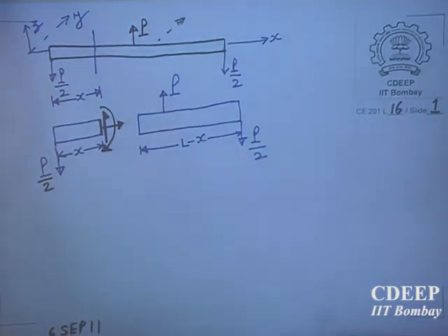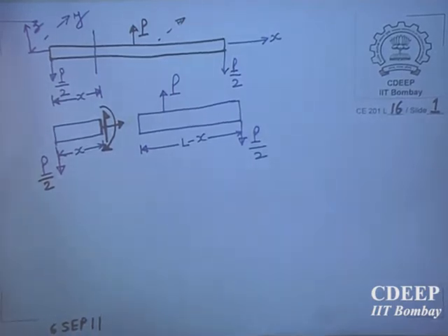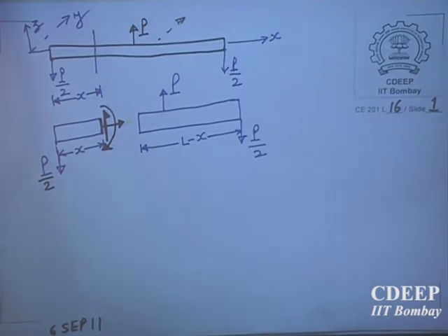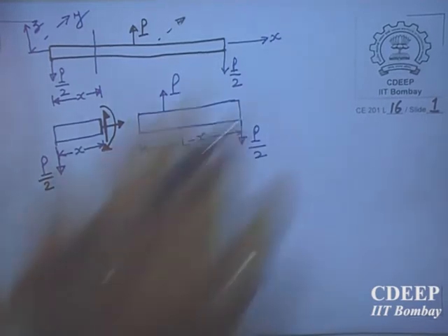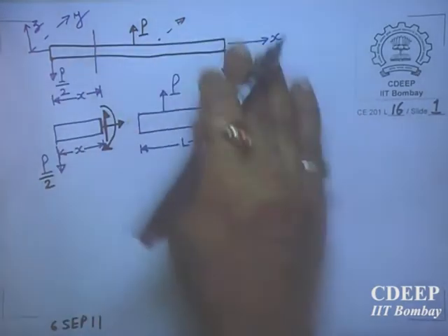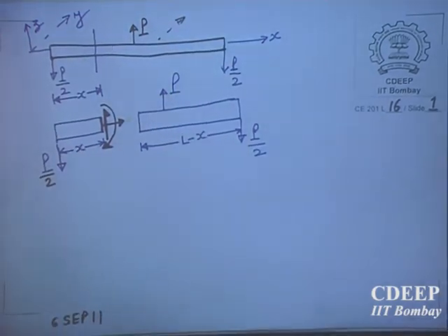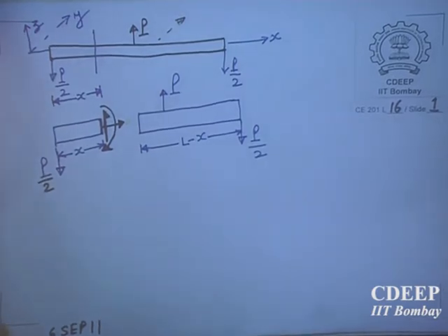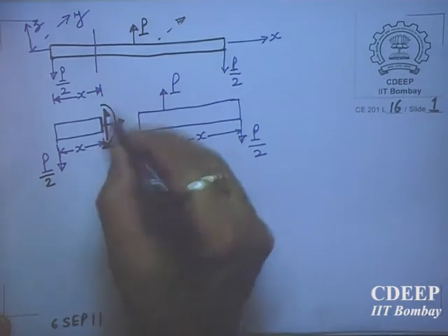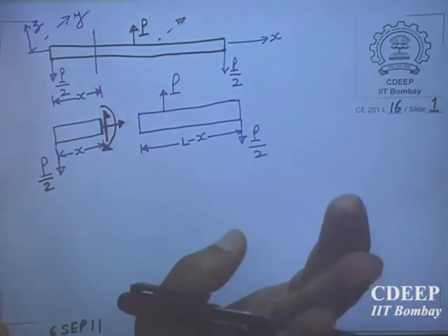So on a planar beam, in general, instead of 6 forces, which we saw in a general member at any cross section in space, which is the most general case, 6. Now here, if the load is planar, if the body is in the plane xz and loads are applied in the same plane transverse to this, then the beam bends, and at any cross section you will have 3 forces like this, not more than 3 at any cross section.